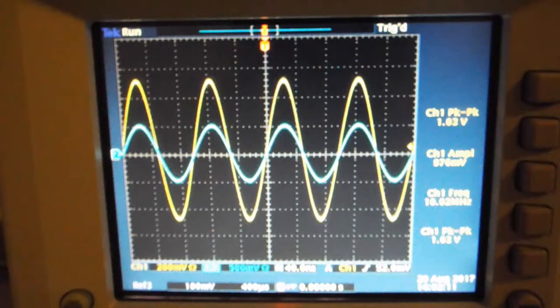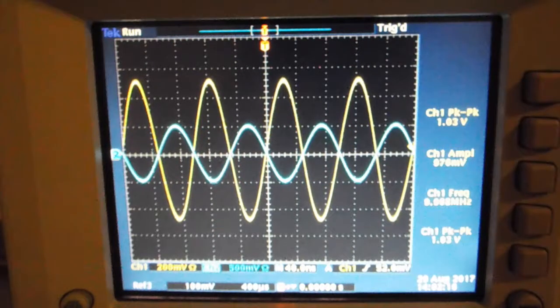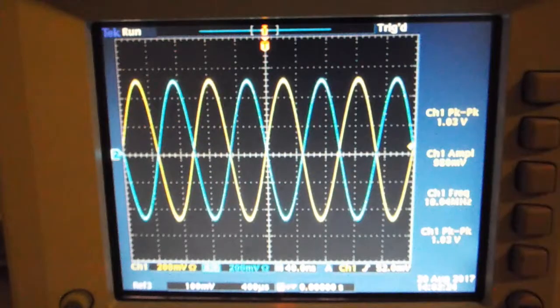Changing the phase of one channel so that the outputs are 180 degrees out of phase with one another, we see that the Model 409B retains phase synchronous operation. Now, if we rescale that one channel, we see we have 2 identical 10 MHz waveforms exactly 180 degrees out of phase with one another. This is during phase synchronous operation.